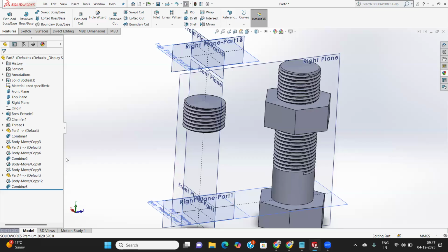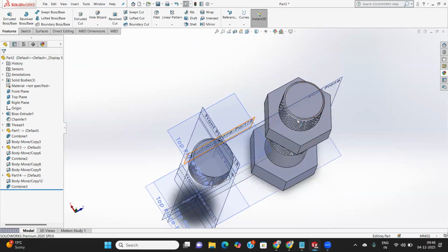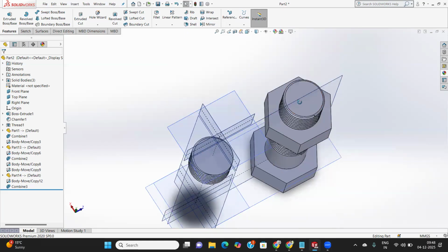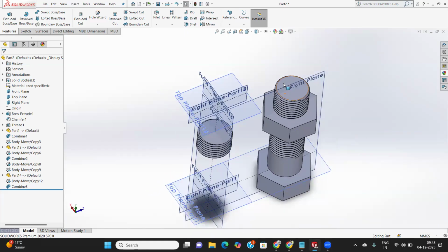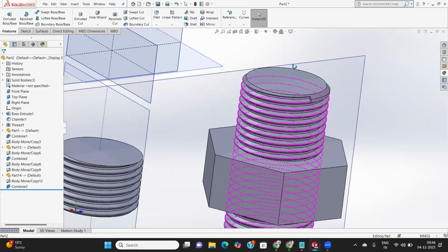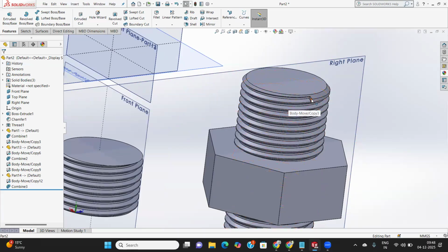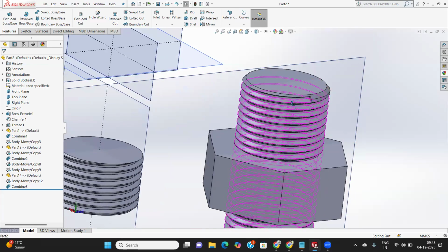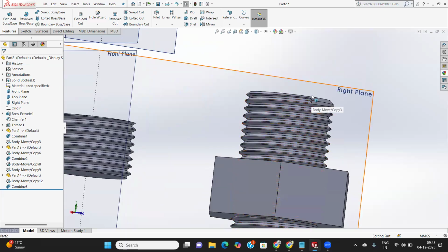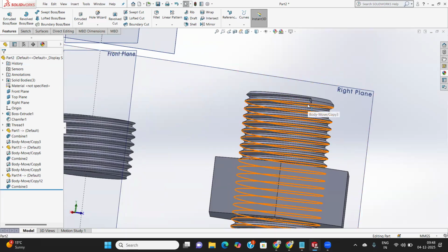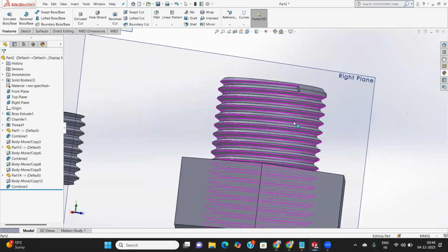In this case, we select M24. M24 denotes a diameter of 24, because I checked and the diameter is 24. And the 2 refers to the pitch distance, from this point to this point. Just select which pitch distance you want. Always remember that if you extrude a thread, you can do the same as the cut thread option, because this will be aligned. That's clear? Yes.